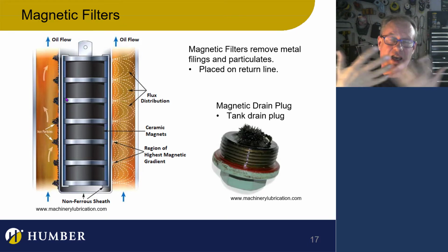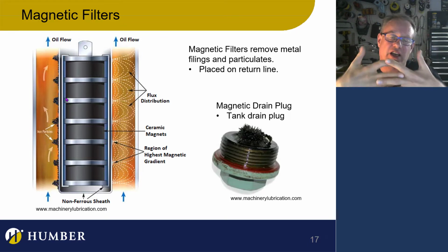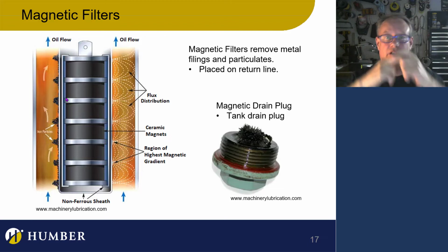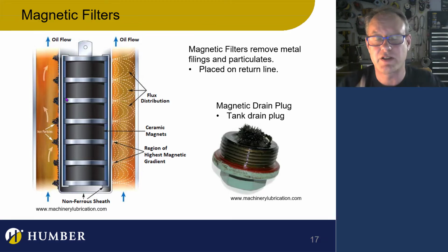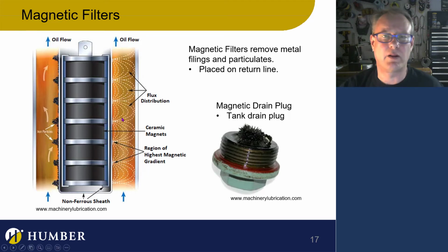Any metal that's stuck, any particulates in there is going to get crushed and is going to create a lot of force in there. It's going to rip off pieces of metal off of your gears. So, yeah, you want to make sure that you get all the metal particulates out. So that'll be on your return line filter.